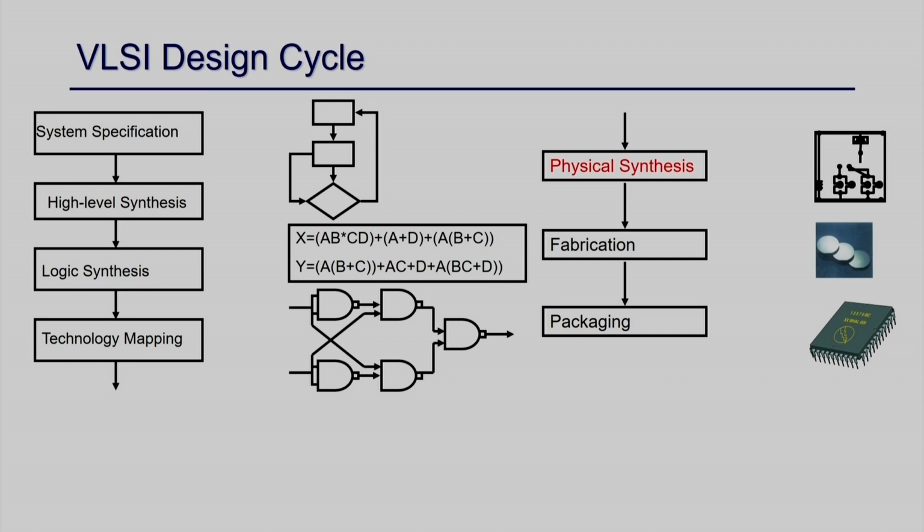So if you think about what we have after the technology mapping step, you have a gate level circuit, which is a huge circuit, and those gates are represented by the cell libraries. If it is FPGA, then it might be LUTs, RAMs, DSPs, or if it is ASIC, then it's the library elements like NAND gate, NOR gate, basic flip flops, RAMs and all, right? So these are the representations.